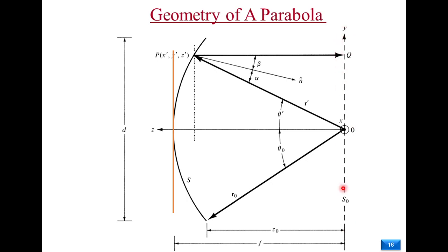So all of them will be in phase, and this means we have a very good, smaller beam width. If we have a mismatch in the phase, we would have a problem because you will have destructive interference and wouldn't achieve the intended small beam width. So this is O, B, B, Q.